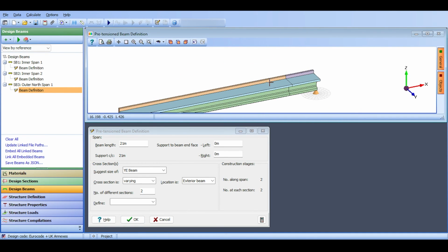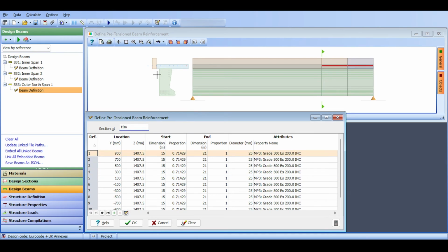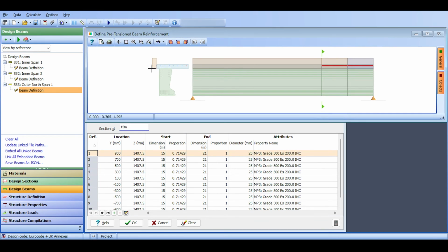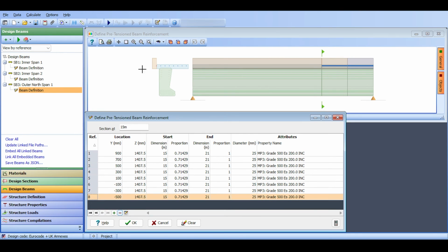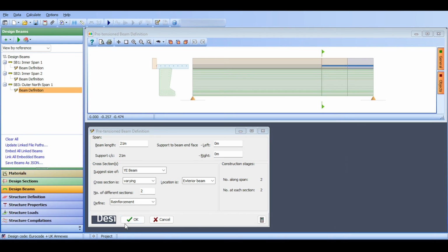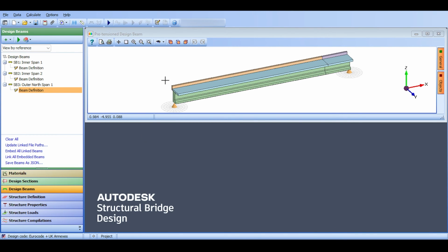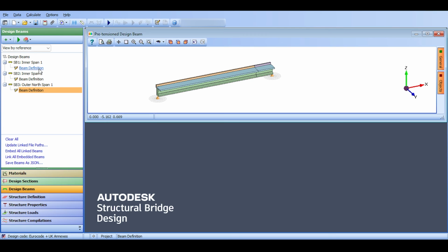Now, still the problem was with the bars. So let's fix the bars. That's a lot of work, right? I click on define, I click on reinforcement and see what happens. Yeah, I can see 2 reinforcement outside here. Maybe 3, but I don't want to delete the third one because it's inside the barrier. Let me select those 2 things like this. And now, how do I delete this? Negative? Is it negative? Yeah, there we go, negative, it seems. Okay, and then okay again. And I think we are done. I think we have done it.